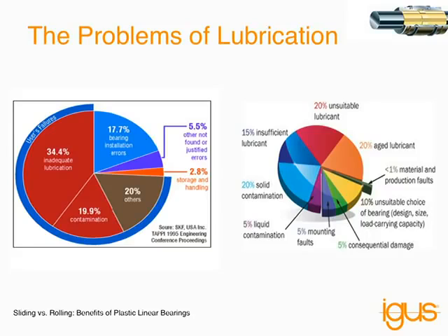There could have been an environmental problem where using the grease in dirt, say, caused an ingress of contaminants into the ball bearing, causing a failure. It could be related to any number of issues, but the number one cause of bearing failure in manufacturing is bearing lubrication related.